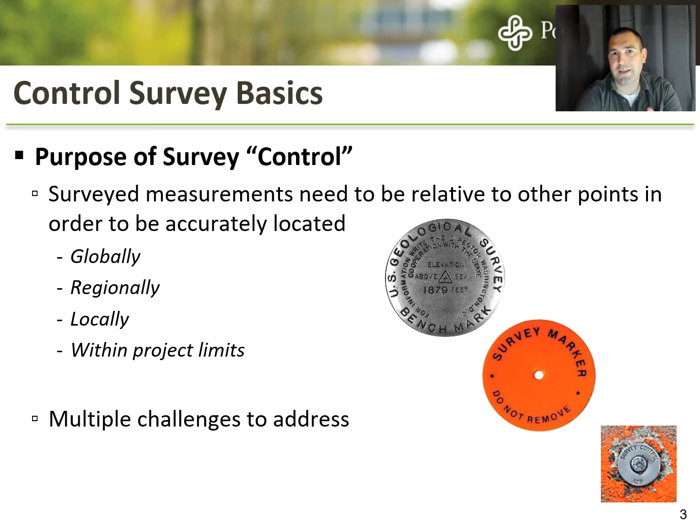And that should seem like it's pretty easy to do, but there's so many different ways to define location and things like mean sea level. What does that even really mean? And elevations are all based off of that. And when it comes down to measuring, latitude and longitude, for example, those are relatively well defined. But when it comes to the shape of the Earth, latitude and longitude are basically, for the most part, assuming that it's perfectly spherical, but we know that in fact it's not. So there are distortions that happen as a result.